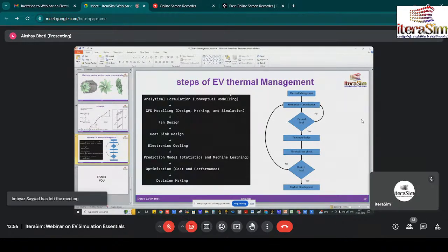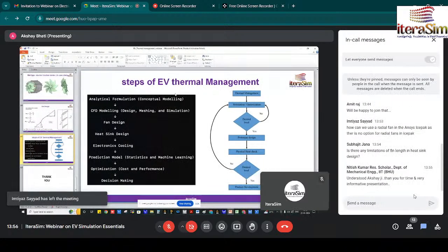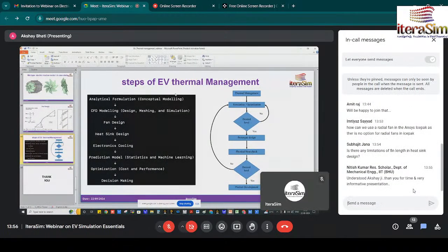And after that, now you have two things, analytical modeling and CFD modeling. You would have some data points that you get from analytic and CFD. After that you can apply that prediction model for optimization. For example, if there is a certain temperature somewhere, how much flow rate do we need to flow over that body to cool it to an optimum temperature.